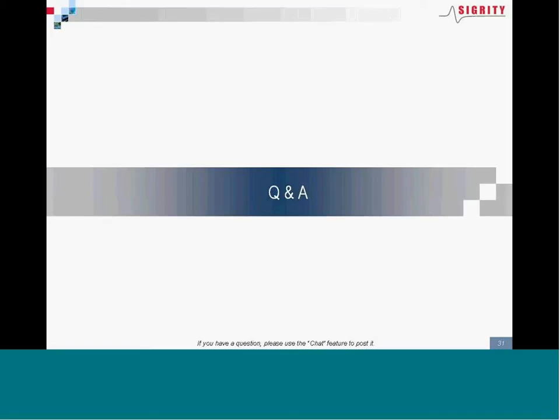So for our approach, as we had talked about, we use traditional time domain circuit simulation to perform that characterization process and generate that initial impulse response, which is very important, obviously, from the channel simulation standpoint that takes place after.